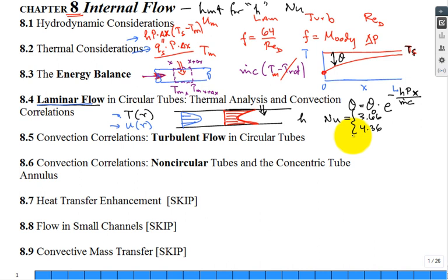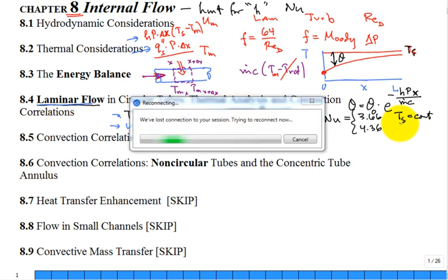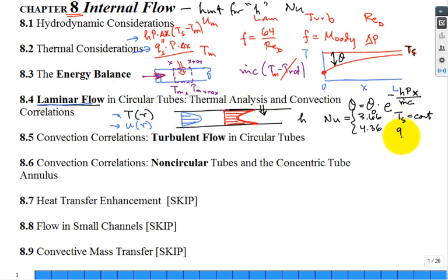that if I have this boundary condition, where the surface temperature is equal to a constant, then I have a constant Nusselt number for laminar flow. Again, the restriction, I'm trying to repeat it because it is important to remember all that. It's just a constant 3.66, and then 4.36 comes with Q double prime at the wall equal to a constant.